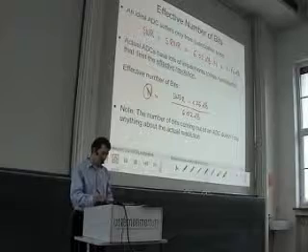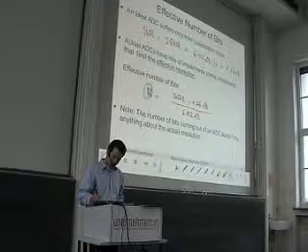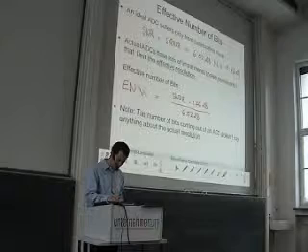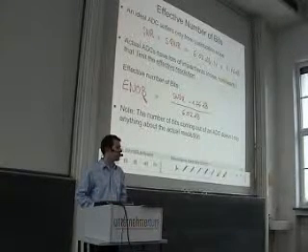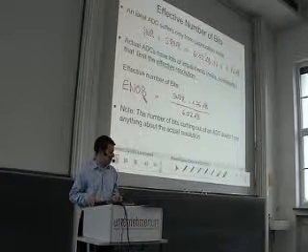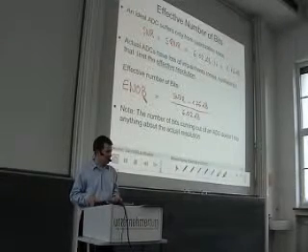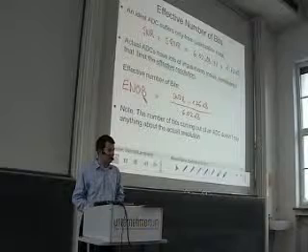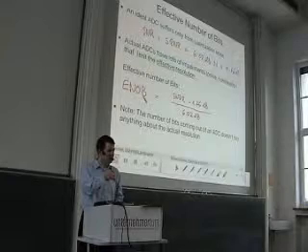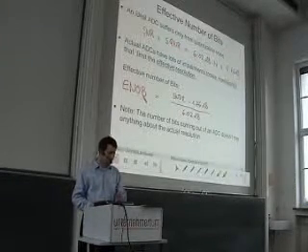Okay? So to make clear what this is, we don't write here n, but we usually write ENOB, which is the effective number of bits. So this is a very important definition. This equation says an ideal ADC, other than the one we are looking at, which has the same SNR as the one we have measured, would have a number of bits given by this ENOB.